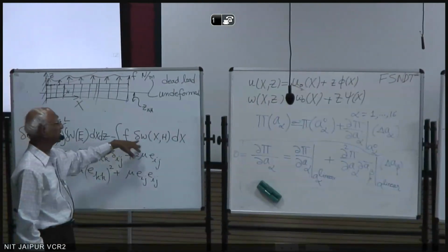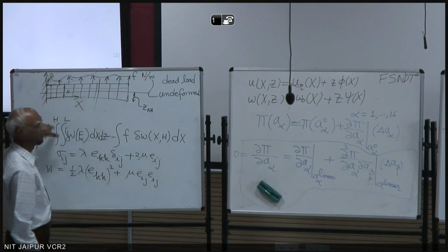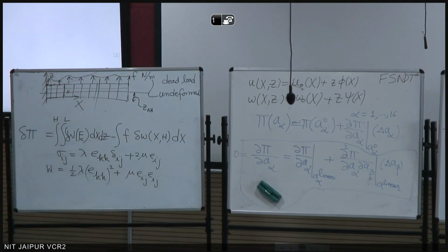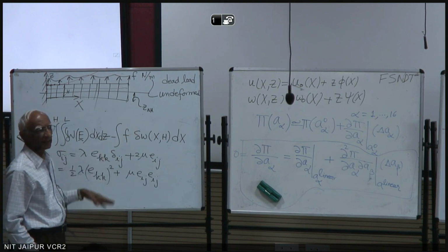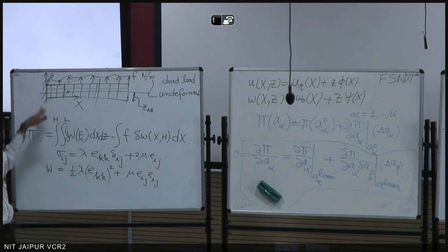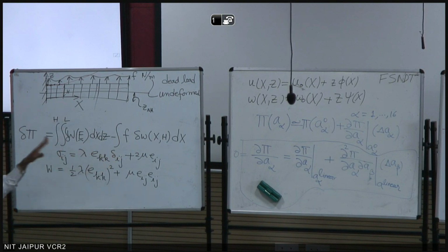And also the W we should take should satisfy the essential boundary conditions. The variation is 0 wherever the essential boundary conditions apply, so when you solve for delta A's, the variation should be 0 on these interfaces. But the A's are constant here. So really the W we choose should satisfy essential boundary conditions.